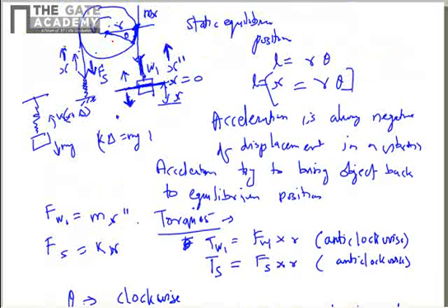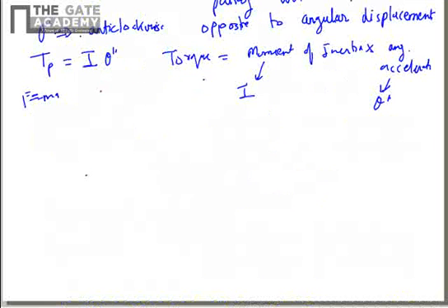So this is torque on the pulley. So the torque on the pulley will also act in the anti-clockwise sense, because the acceleration is in the opposite direction to the displacement. So theta double dash is anti-clockwise. So Tp equal to I theta double dash is also anti-clockwise. We have considered the acceleration of the pulley also.